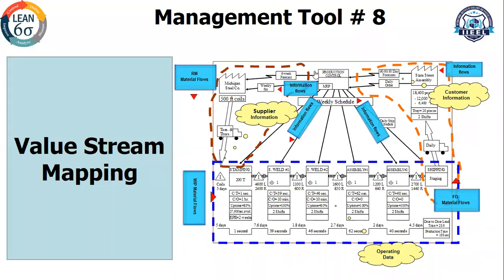Value stream mapping is an expert area. So you can learn slowly, but you should first know how to draw, and you have to draw it actually how it is there on the site. So you have to do a walkthrough to draw the value stream mapping. You cannot sit in the room and draw.